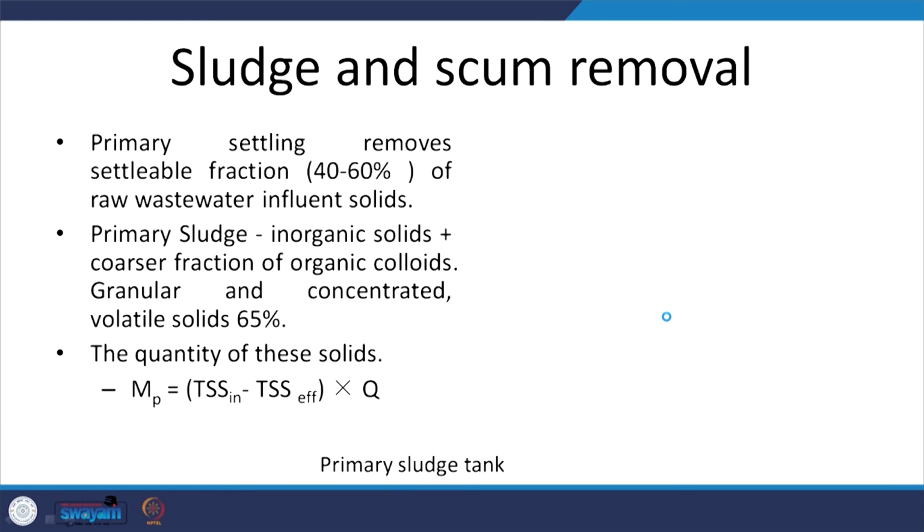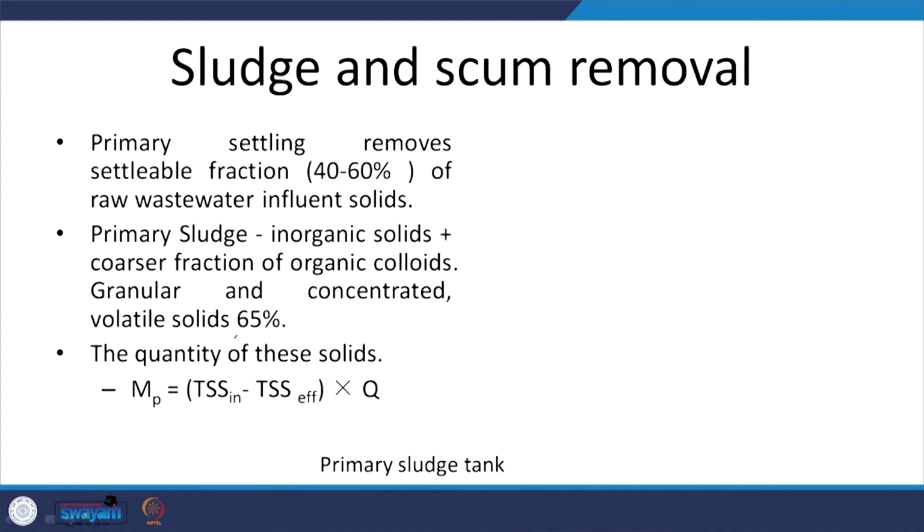And then sedimentation tanks, what is it that we are trying to do? We are primarily trying to remove the suspended particles, but along with suspended particles, some organic content which is suspended or adsorbed onto these suspended particles will also be removed. And again, will we have removal of all the suspended particles? Not really. So we typically have a fraction being removed, right?